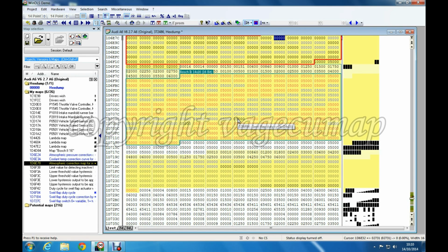And if the only fault was that they were jamming before and throwing up error codes, then if you're lucky they now will not do that, because they will now sit in one position. But the problem is if they already have reported to the ECU that they are jammed in a particular position, or that they've gone open circuit, you will still get error codes, and so you will then need to delete the error codes that you've got to clear that away.